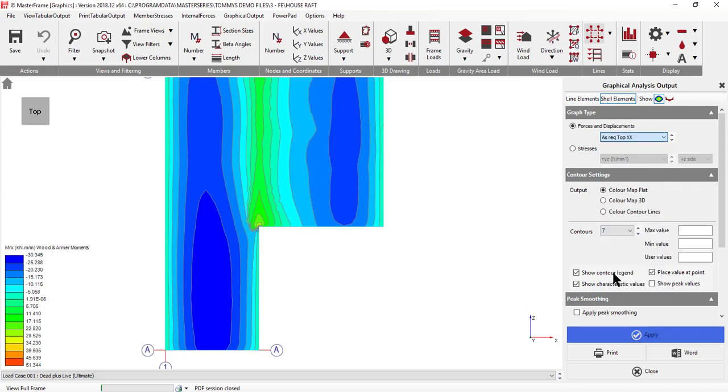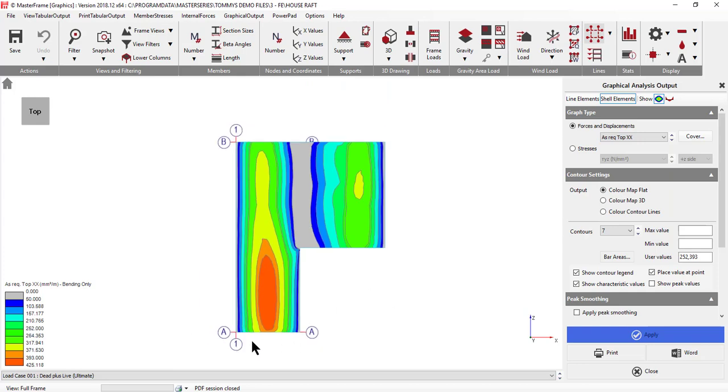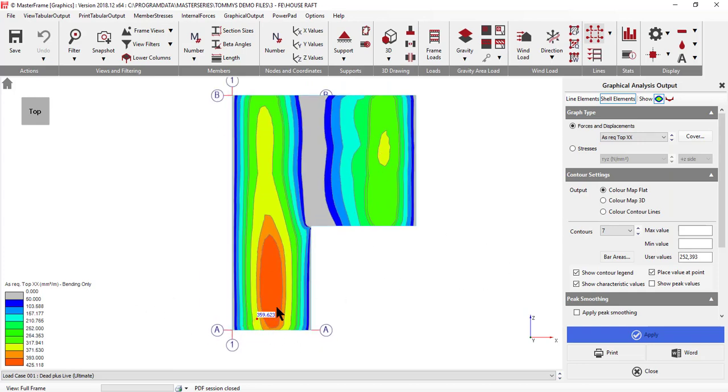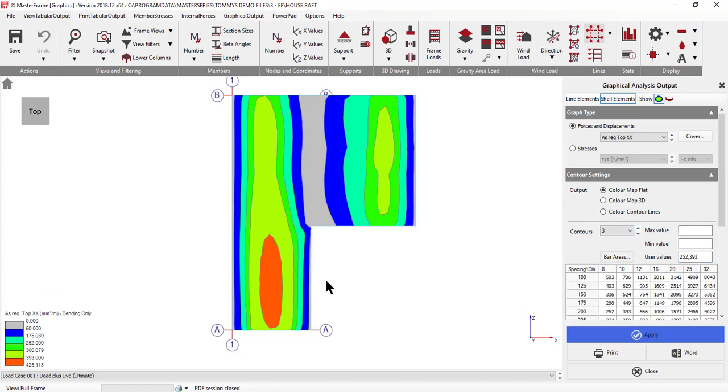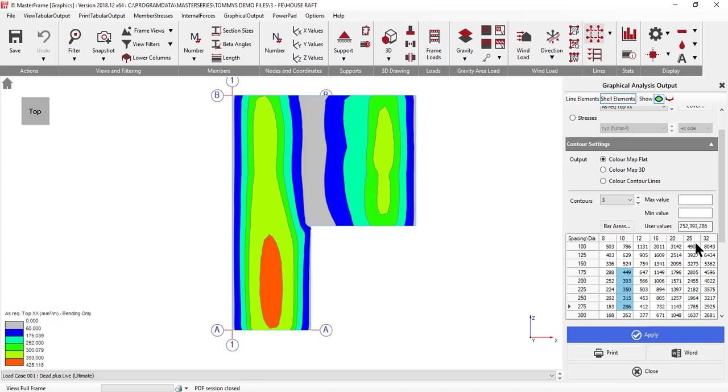We give you the tools to do that automatically because we allow you to say what is the area reinforcement. So you can see what is the top steel. So we're needing up to 400 mil, so we're going to need a wee bit bigger than the 393. So if I go down to a low number of zones and I click in here and I want to add in after 393s, I would either pull the 12s down to 440 in there. I didn't get the 440. I clicked on the wrong one. There we go. And just apply.